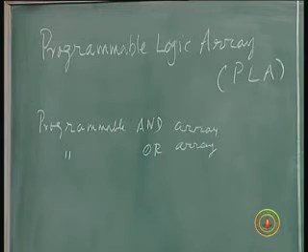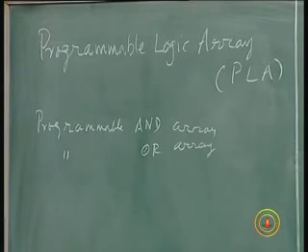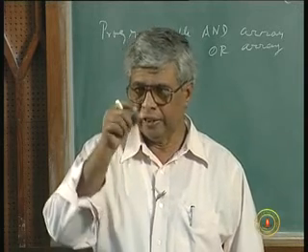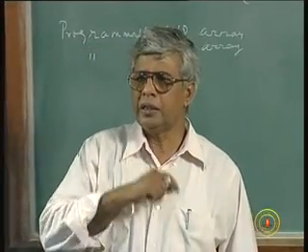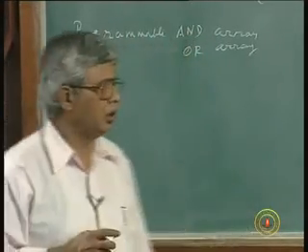For that given set of outputs, look at the outputs to be generated and only those minterms will be generated. Do not even generate the other minterms, meaning I can reduce the hardware. This is the concept of programmable logic array.